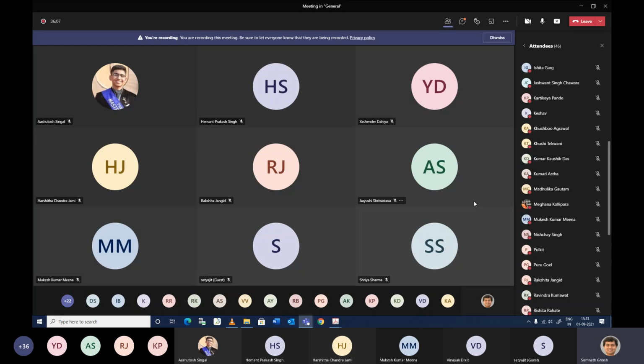The data set means, for Bernoulli's experiment, the heights for the 7 different tubes, as well as the volumetric flow rate. Mukesh will circulate those data to all of you. All the equations are nicely written down there. You just need to calculate step by step all the values and then provide them in a tabulated form.